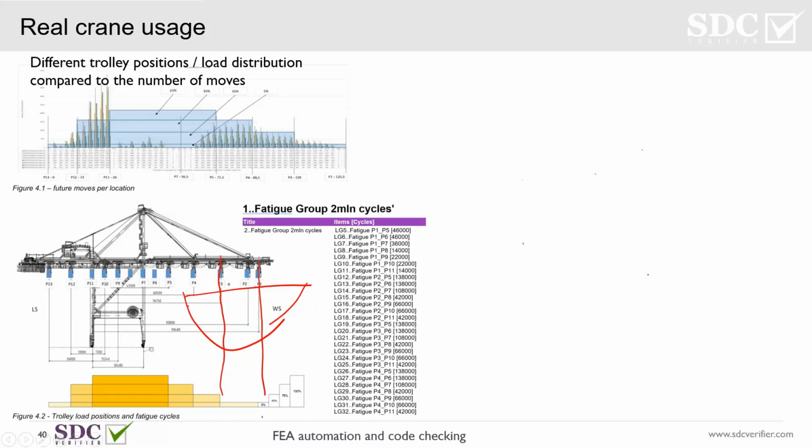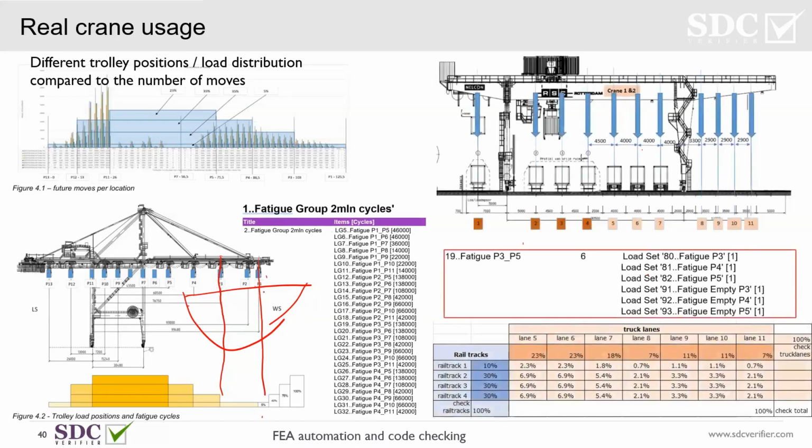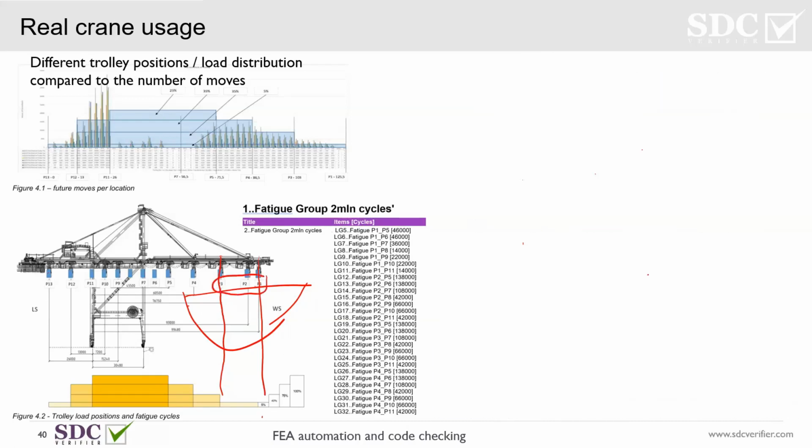We see that from position number 1 to position number 3, we're using only 5% in our case, which can vary to 10 or maybe even 15. So we put it in one load group and say that all the stress ranges calculated within this range should be summed as many times as specified in our number of load cycles, which is only 48,000 load cycles.